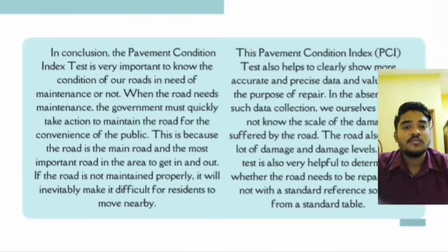This PCI test also helps to clearly show more accurate and precise data and values for the purpose of repair. In the absence of such data collection, we ourselves would not know the scale of the damage suffered by the road. The road also has a lot of damage and damage levels. This test is also very helpful to determine whether the road needs repair or not, with the standard reference from the standard table. That's all from us. Thank you.